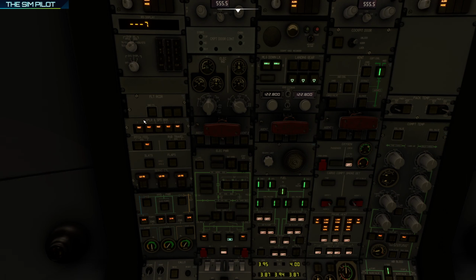Flight recorder, we don't touch this. Spoilers, this panel, as we discussed, is various flight management computers or flight computer systems. We will leave them as is. Fault lights are okay for now. If you remember the Airbus, it has a lights out layout or setup where if it's a white light, which in this case means this switch is not in the expected position, you need to press the switch or turn the knob to extinguish this light.